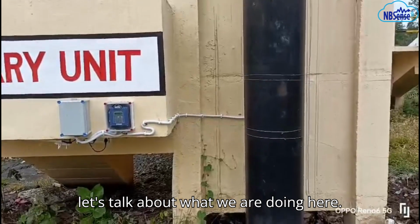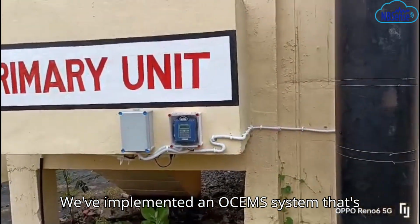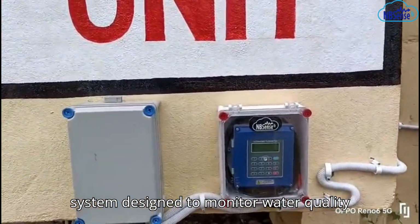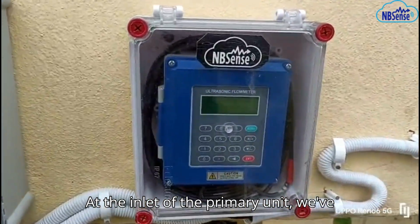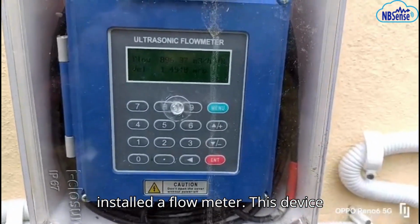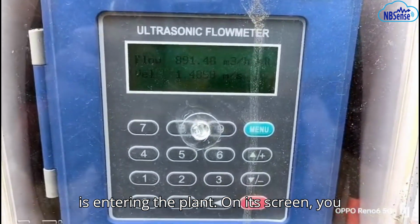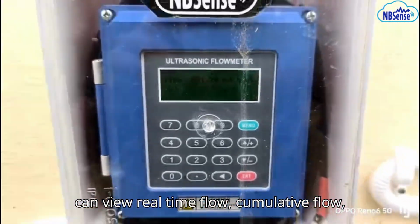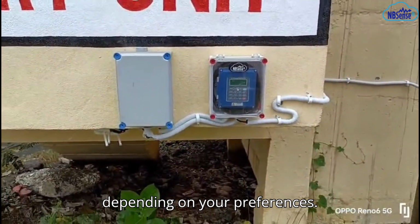Now, let's talk about what we are doing here. We've implemented an OCEMS system, that's an online continuous effluent monitoring system, designed to monitor water quality at every stage of the treatment process. At the inlet of the primary unit, we've installed a flow meter. This device continuously measures how much wastewater is entering the plant. On its screen, you can view real-time flow, cumulative flow, monthly, quarterly, or yearly data depending on your preferences.